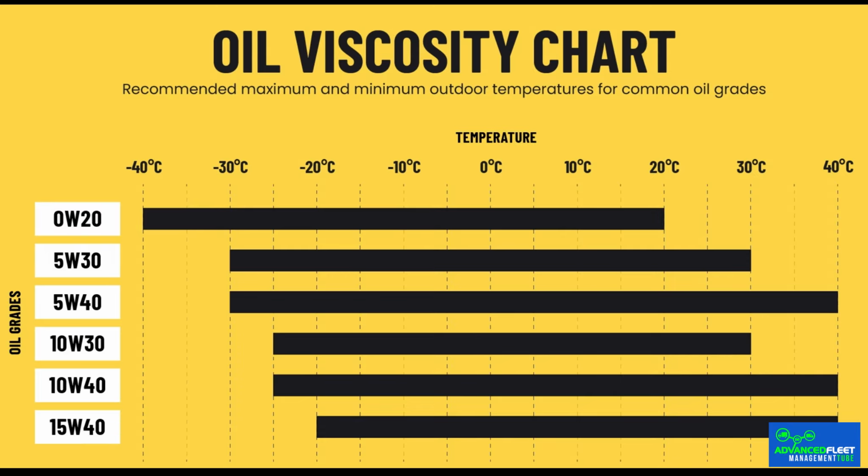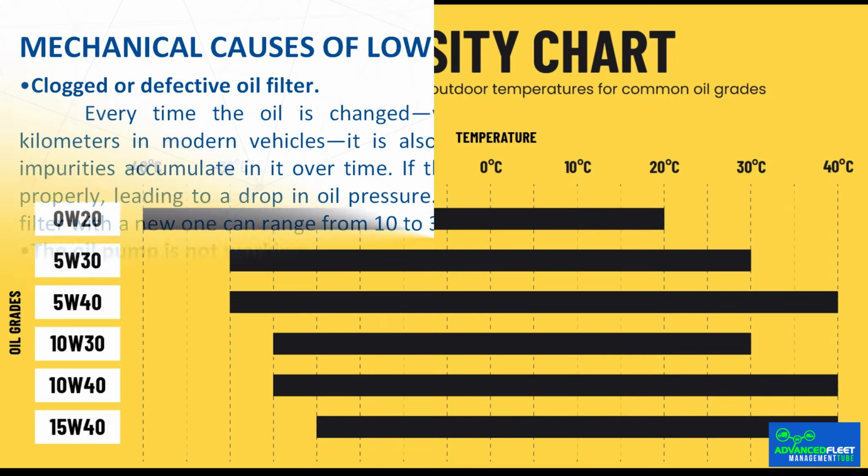If the oil is excessively viscous, its density will be significantly higher, which will hinder the circulation of the oil, typically pumped by a pump located in the oil pan, through the system. If the oil has lower viscosity, its circulation speed will be too high compared to what is required, resulting in inadequate pressure. It is essential to use the oil recommended by the vehicle manufacturer to ensure optimal engine performance.